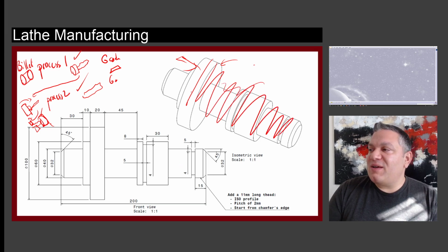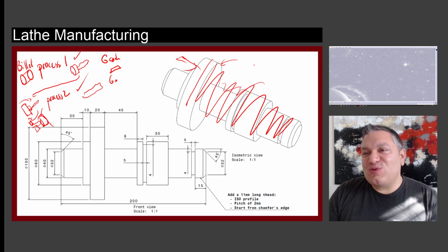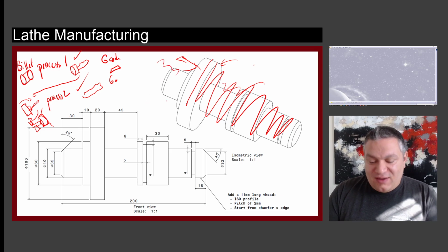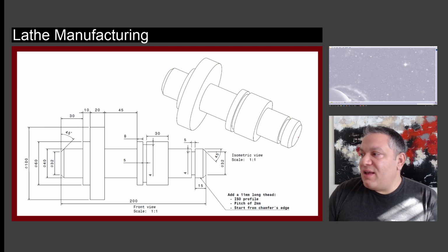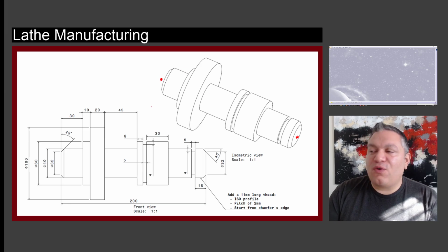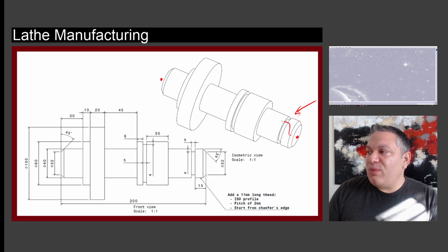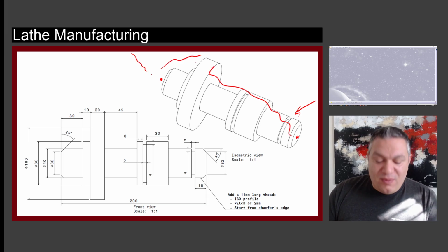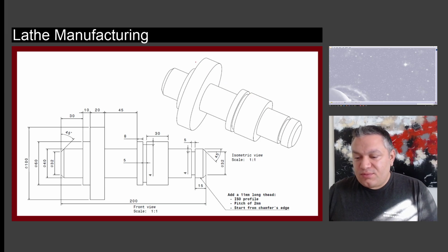A robot comes, picks it up, takes it to another fixture, loads it, gets it attached, and we're going to do the other part from the other side. So this means that we're going to have two programming points for our two codes, because we're going to be coming from that side to manufacture here, and we're going to be coming from that side to manufacture here.